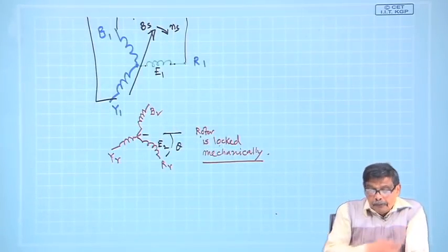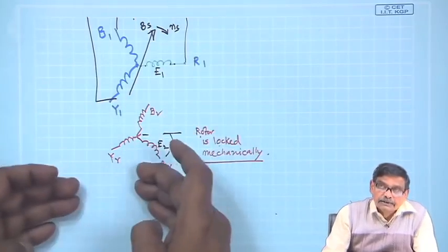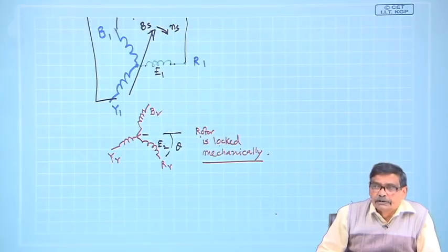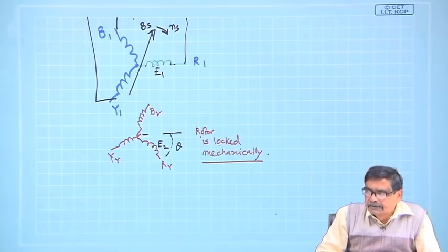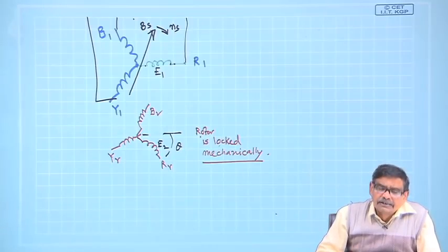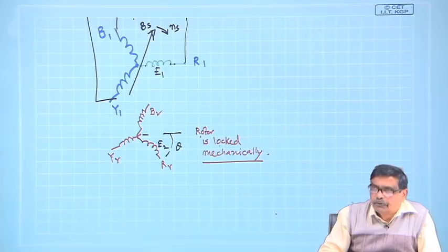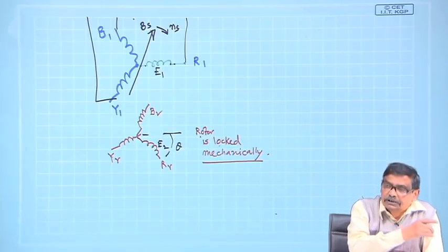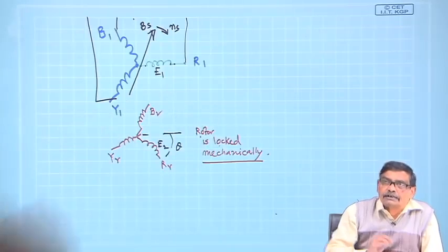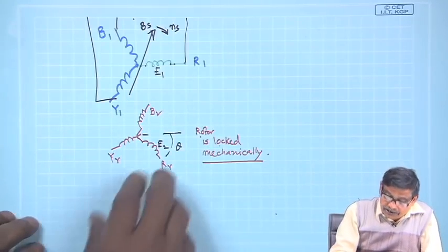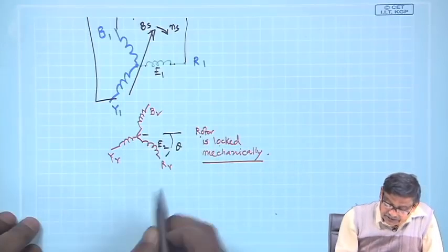Therefore, with this arrangement, this is called a phase shifter. Suppose there is an input 3-phase voltage, and for some reason you want to get once again a balanced 3-phase voltage and phase shift it with respect to the actual supply voltage by say 30 degrees or by say 90 degrees, whatever you want, you give this shift.